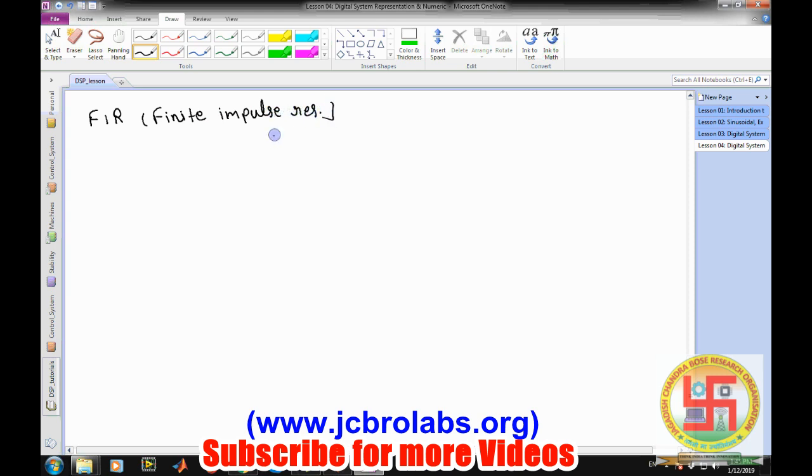So in our case, if the impulse response, this h of n, is of finite duration, that means it exists from 0 to, let's say, N length, and N is less than infinity, then the system whose impulse response is finite is known as the FIR system. Similarly, we have another system, that is the IIR system, also known as the infinite impulse response system.